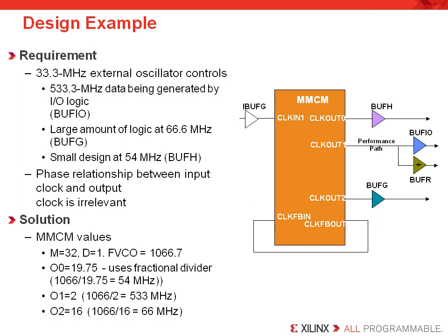It must be distributed on a BUFG since its logic has a high fan-out and probably spans multiple clock regions, so there's no choice there. It has to be in a BUFG. And as you can quickly discern, the key decision to make was what frequency we have to generate for the VCO. That determines what is possible with the MMCM.